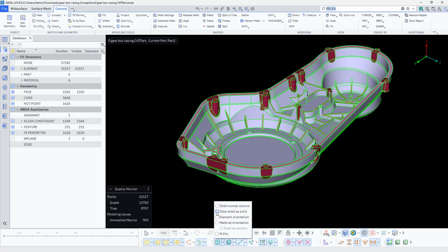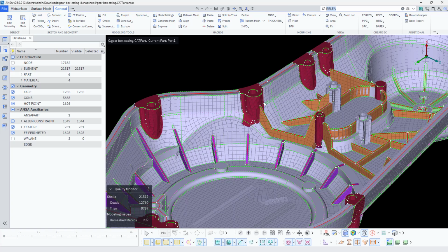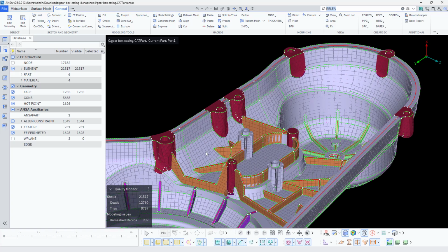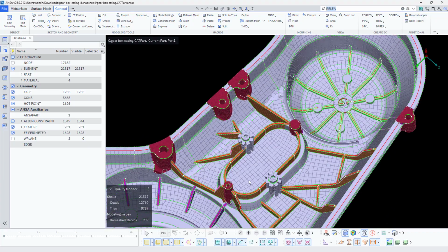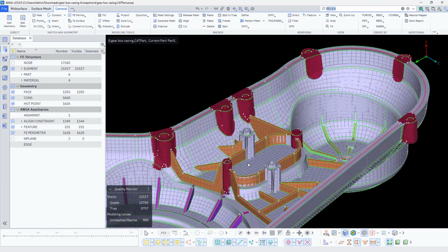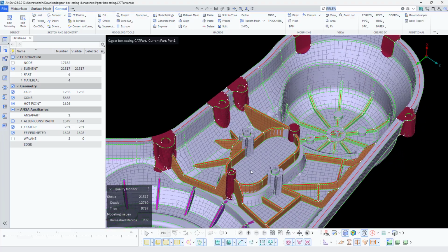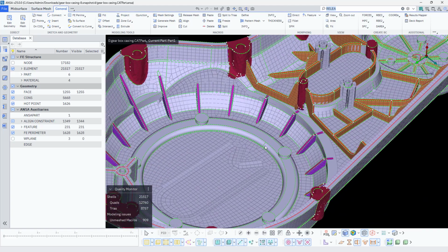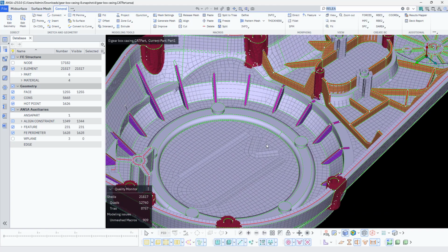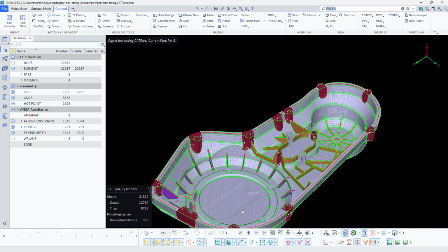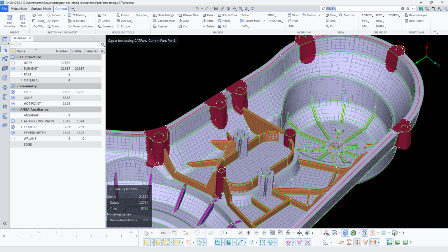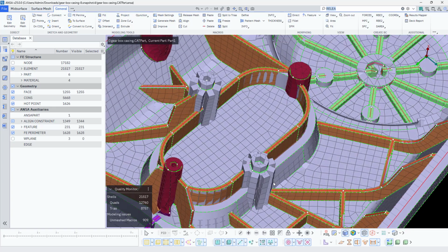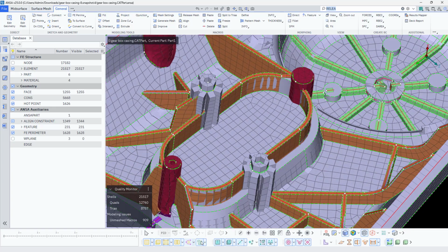So you can just switch here to draw cell as sorted, and you could see all this region is properly captured. And here we have some issues with the mount. As I told, we have created it manually, right? So it will take the by default PID. So what best we can do is we can just change it to the shell thickness. Anyway, these are the mounts, right? So we can assign it as minimum thickness, and anyway it won't be considered as a shell. So we have the mounts, right? So we're going to define the solid properties for that.